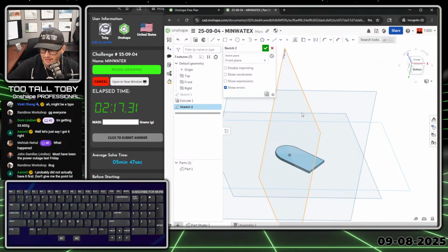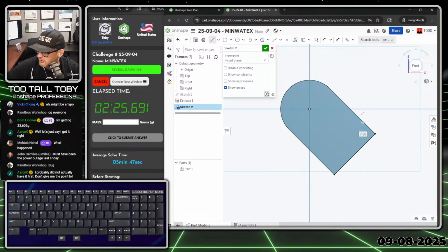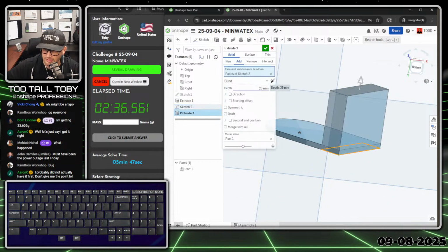That is N, not control N. We'll get normal 2 here, and we'll create this geometry here for that second shape. So we'll come up in this direction. Let's input that dimension right away, 9. Come back over here in this direction. See how we're getting that perpendicular and coincident. See, if you just take a second and make sure that you're getting those relationships while you're sketching, it can really save you a lot of time. So bring that up to 6.